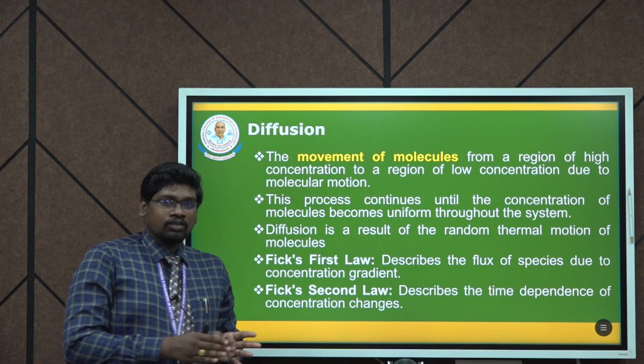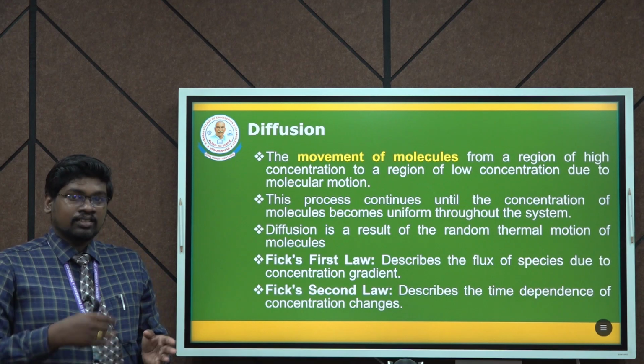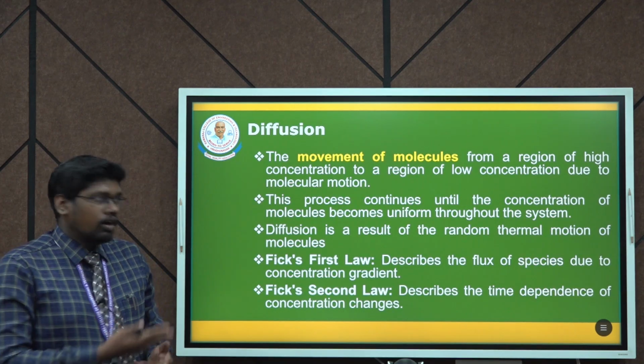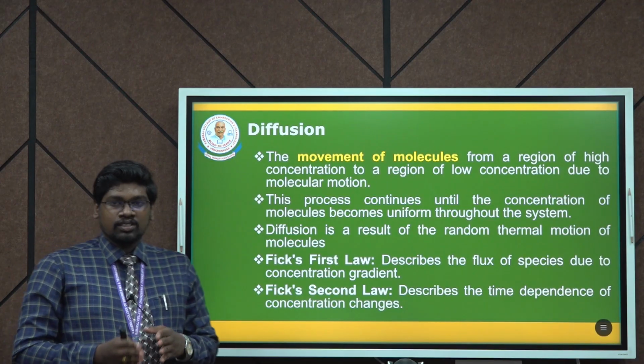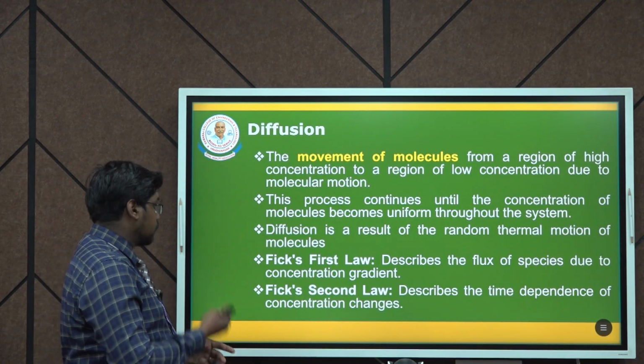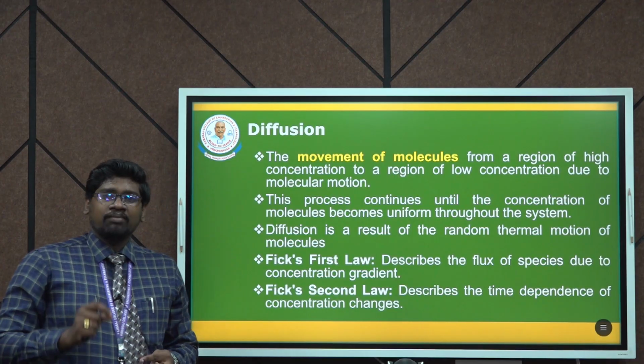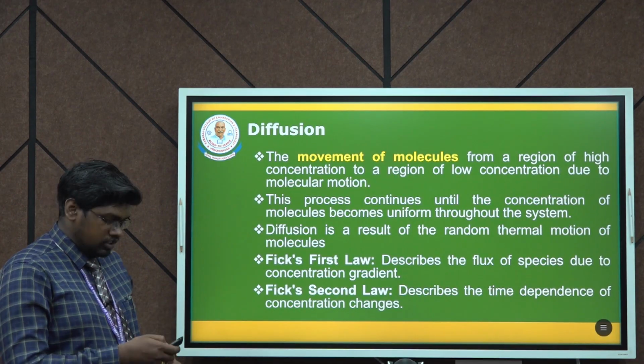The diffusion process is governed by Fick's first and second law, whereas Fick's first law describes the flux of the species due to the concentration gradient, the movement of the species due to the concentration gradient, and Fick's second law describes the time dependence of the concentration changes.